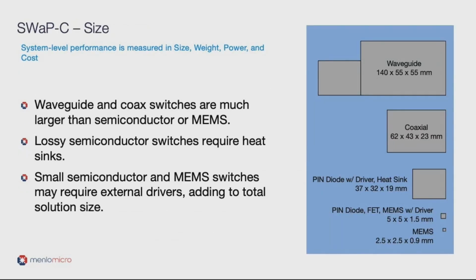The next specification I'll talk about is the size of the switch solution. On the right, you can see a to-scale comparison of different RF high-power switches of the different technologies. Of course, the waveguide and coaxial mechanical switches are much larger than the semiconductor pin diode or MEMS switch solutions. But an important consideration is the total solution size and not just the switch component size. A switch that has high losses and requires a heat sink or other thermal management that grows the size of your solution will grow your overall system.